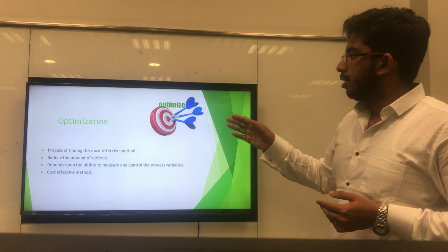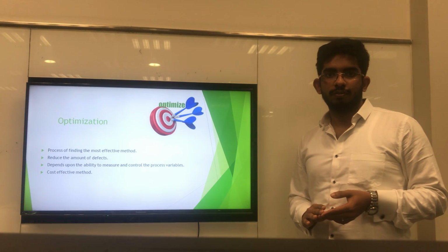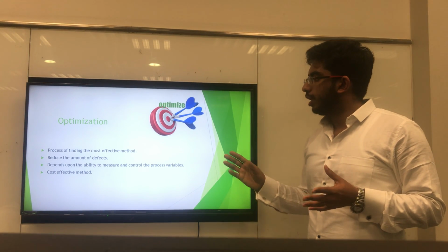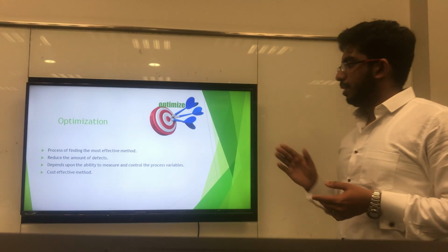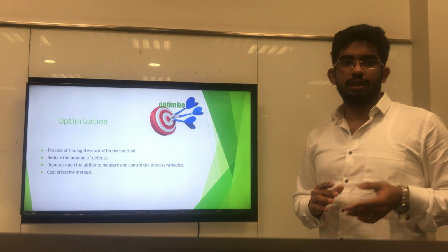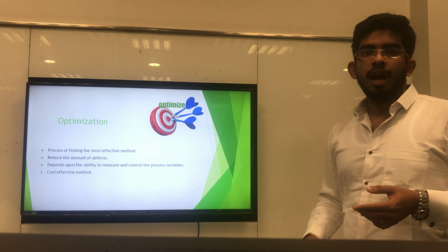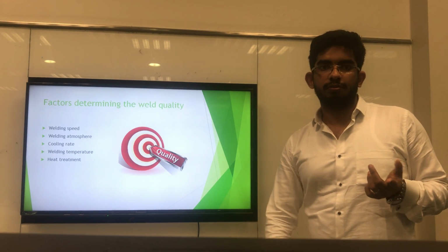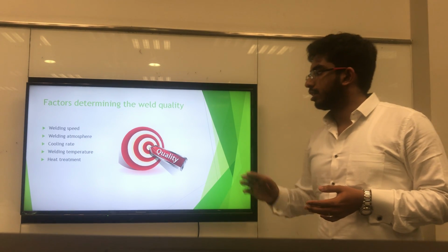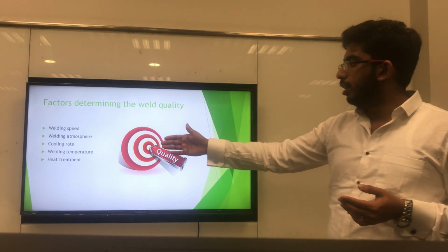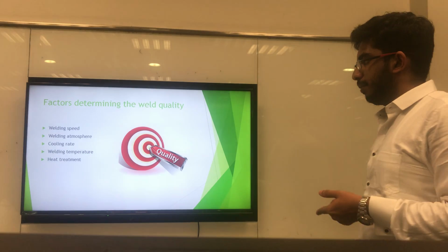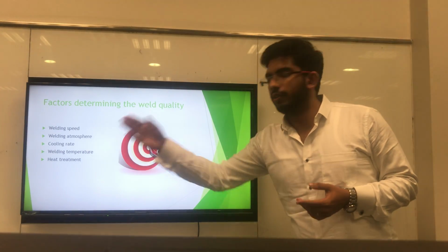This leads to the idea of optimization. Optimization is nothing but finding the most effective method. The optimized parameters can reduce the number of defects, and it is very cost effective. The major factors that can be optimized are the welding speed, welding atmosphere, cooling rate, welding temperature, and heat treatment. Consider the welding temperature.